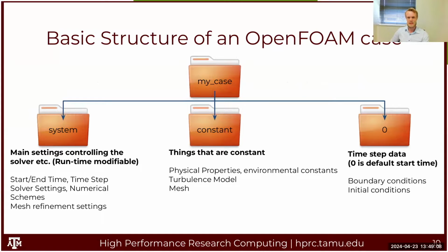So this is the basic structure of an OpenFOAM case. We have a folder, which can be called anything. In pretty much every OpenFOAM case, we have 3 basic folders. We have one called system, which contains the main settings controlling the solver. We have a start and end time, what's the time step, what numerical methods and numerical schemes we are using, and what settings we are using for mesh refinement.